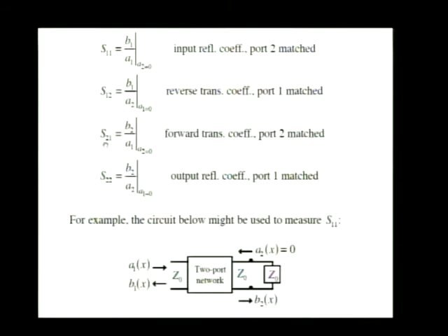Is that why your speakers have to match like your power amplifier? Have you ever heard of speakers matching the amp? Yeah, absolutely. Have you ever heard of, what's the common, 25 ohm speakers? 5 ohm speakers? 8 ohm. 8 ohm. There we go. I couldn't come up with that for some reason. 8 ohm speakers. Yeah, they always talk about 8 ohm speakers. That's what they're talking about. They're talking about that speaker matching the output impedance of the amplifier for maximum power transfer, so that power comes out of that amp but doesn't get reflected back in. Absolutely.